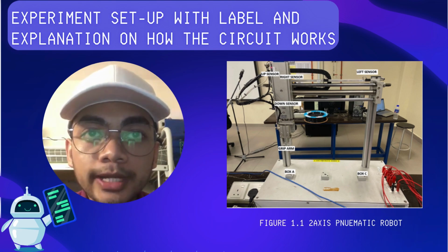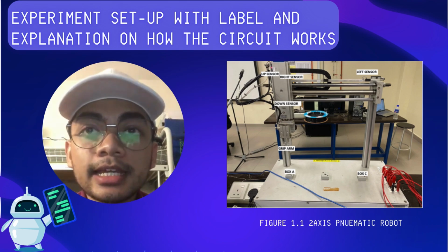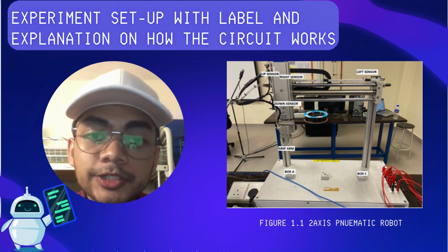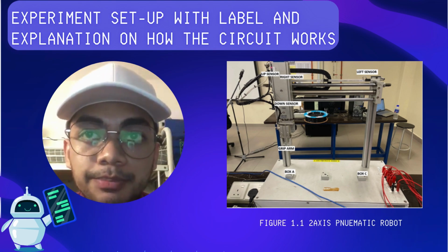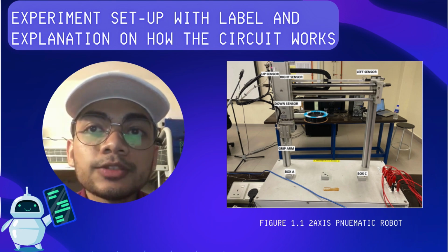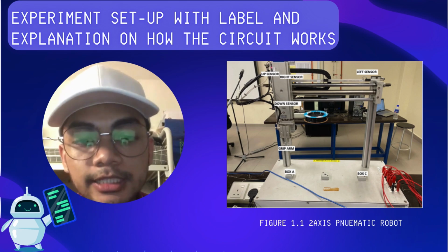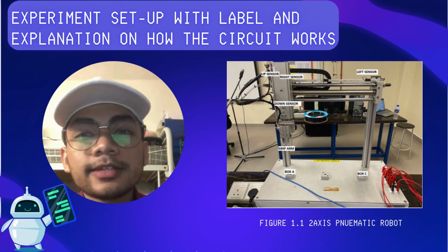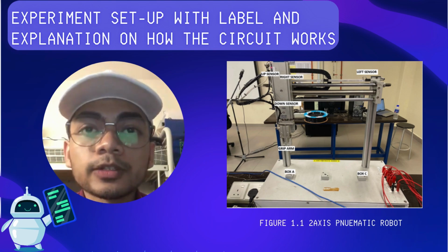After the arm went up, the right sensor is energized and without any delay, the down sensor is energized again to go down. After 3 seconds, the grip will open and drop the object picked from point A at point C. After releasing the object, the up sensor is energized again and the arm will move to its initial state, which is at point A. This robot will continue this cycle for 10 times.